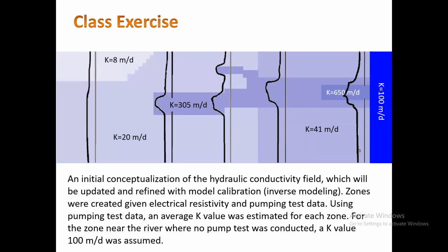Then I also have another boundary which is here, and this is again another no flow boundary. This is the bottom of my aquifer. I have a confining unit here, so this is also a no flow boundary. Q that goes down is also equal to 0. Basically, that's all I'm doing.